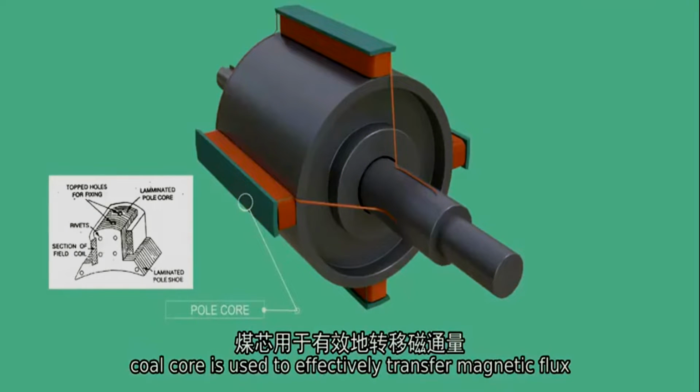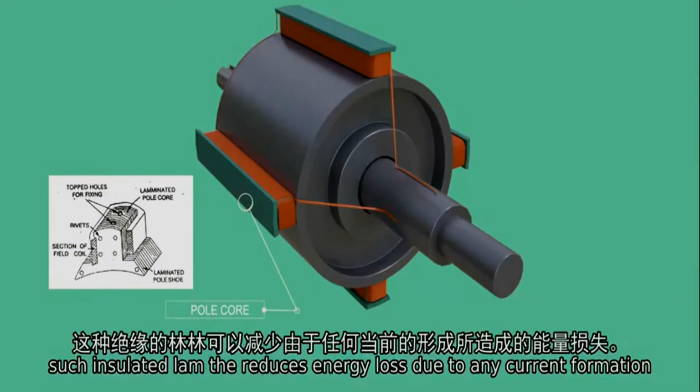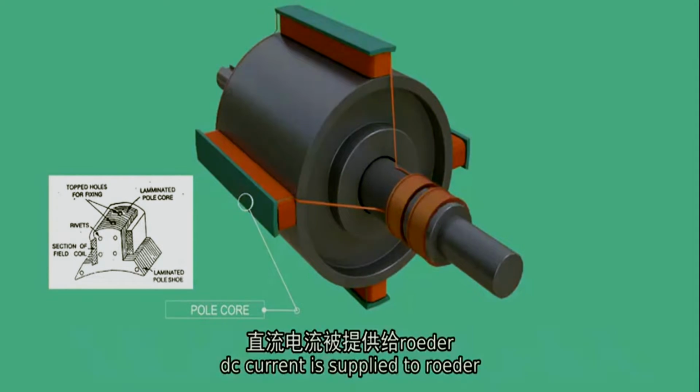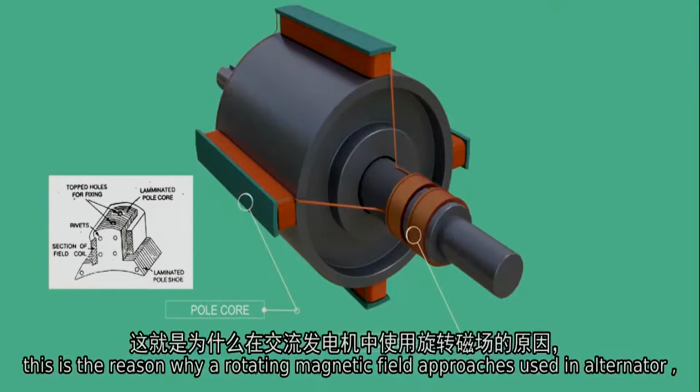Pole core is used to effectively transfer magnetic flux, and they are made with fairly thick steel lamina. Such insulated lamina reduces energy loss due to eddy current formation. DC current is supplied to rotor, with a pair of slip rings. This is the reason why a rotating magnetic field approach is used in alternator.